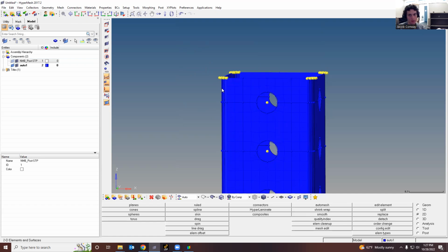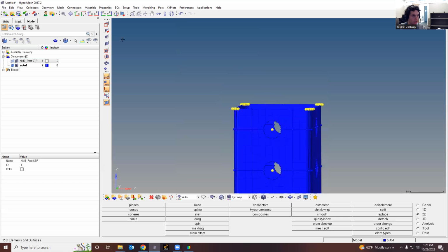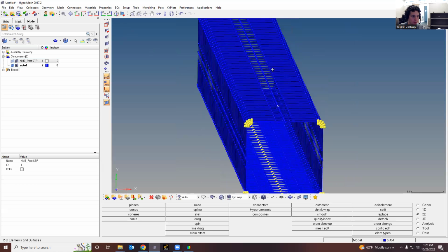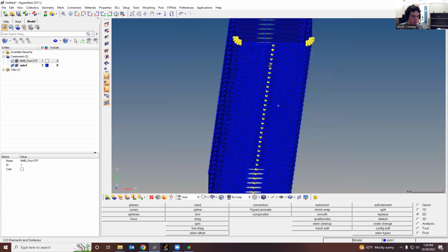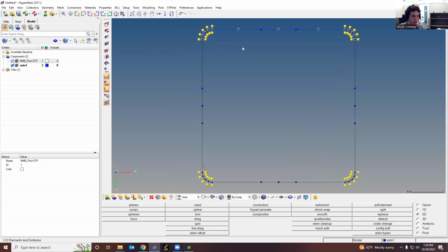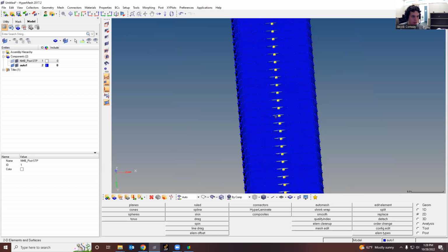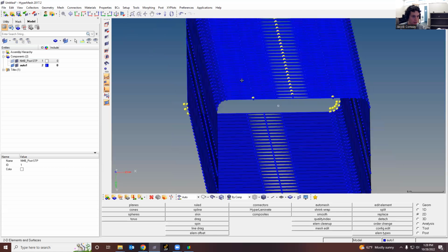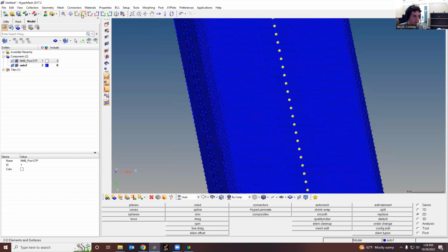So if you were to do all 4 faces, it would take you an hour plus, even if you get really good at it. So yeah, we can go here and make sure which face is meshed. It's the bottom face. I don't like that. So I'm going to go like this. So the top face is meshed. If I click on that, double check. Yep, there we go.